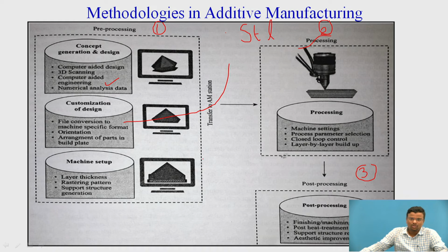So the closed loop is to take the 3D model from the CAD software, convert it into maybe the .stl or maybe the .obj data exchange format, and provide it to the additive manufacturing machine tool, so that there will be the development of the product by the layer approach.